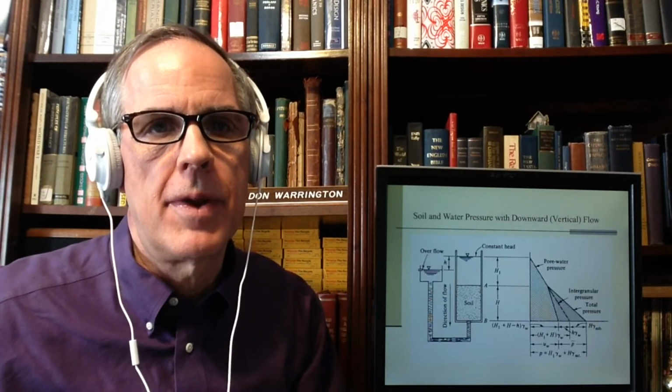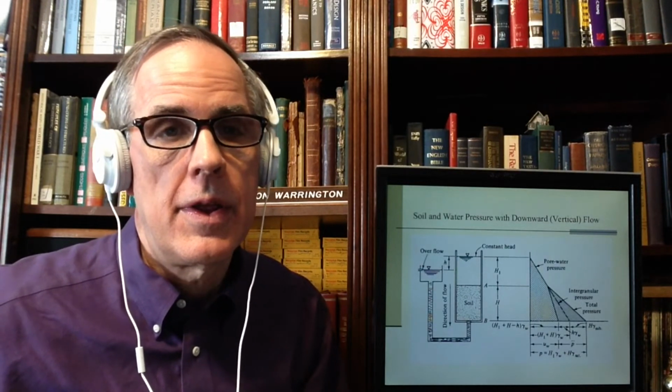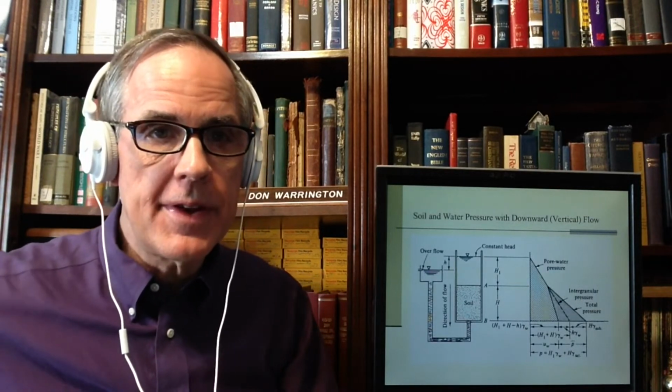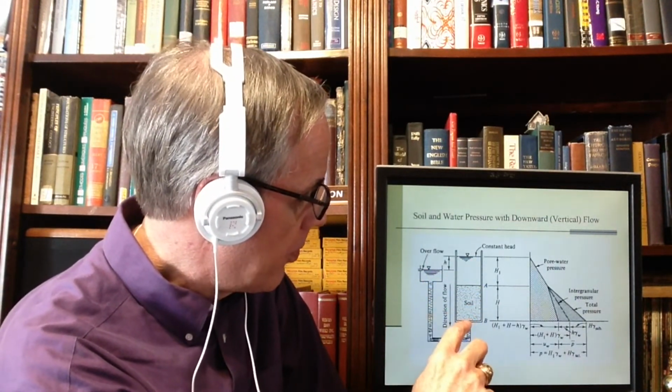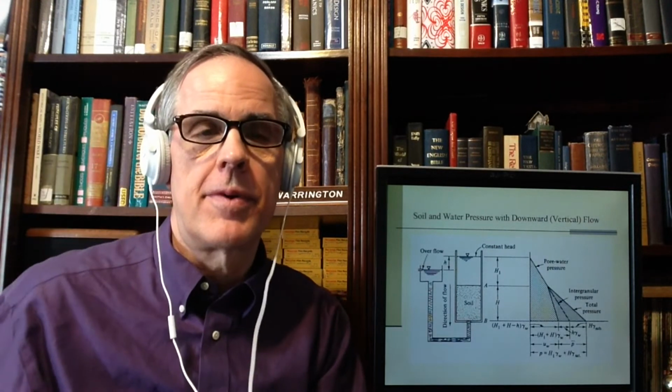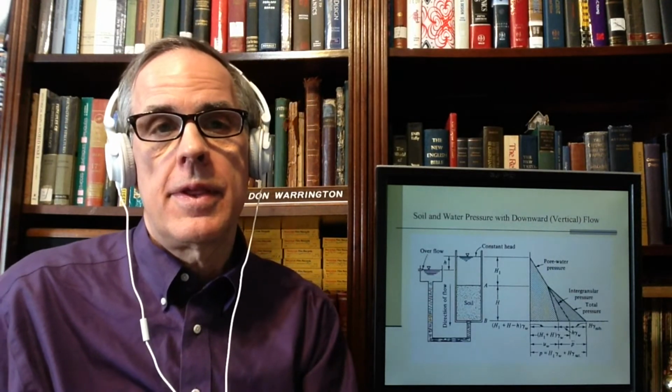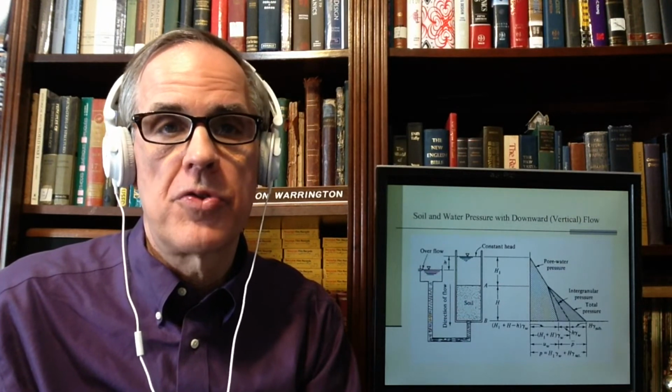Now, obviously, that's not physically realistic, but what it tells us, though, is that with downward flow this way, the pore water pressure decreases at the bottom. If the pore water pressure decreases, the effective stresses increase. And if the effective stresses increase, like a case of capillary rise, which is kind of the flip of this problem, then the particles will be drawn closer together.